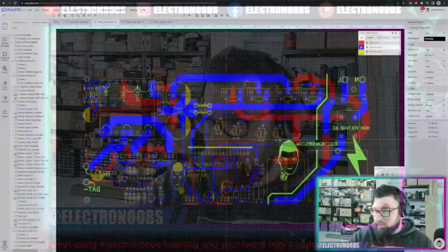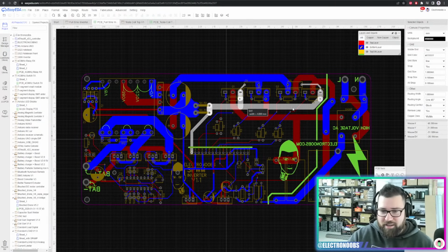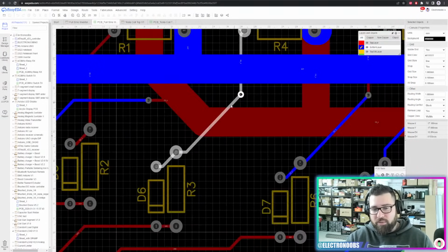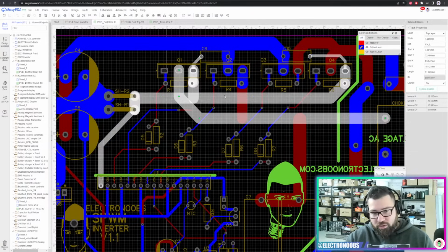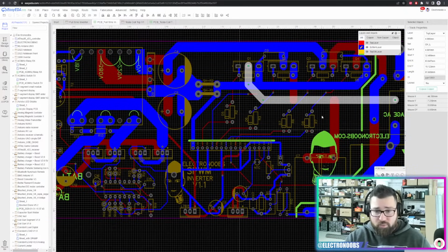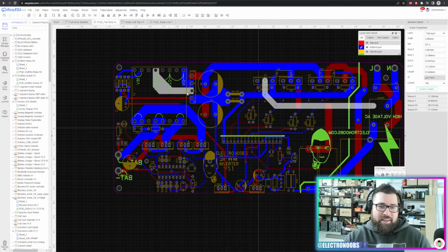Let me just change to the desktop view. This will be the schematic, because I don't want to stay here 3 or 4 hours. When I designed this PCB, I spent about 4 hours entirely, and only to make the tracks, I think I spent about 2 hours. So you don't want to stay here and see me route all these tracks in 2 hours. So what I will do is, for example, show you how to make the small tracks for signal, how to make the power tracks, how to expose the copper, how to change the angle of the tracks, and so on. Some basic placement of the components and the tracks, and then we jump directly to the final schematic, because otherwise we will be staying here for hours.